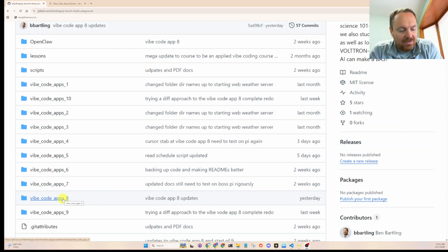Usually the mechanical engineer spec will say we need to create alarms, we need to log data for about a month, or some kind of specification on that. We need to dial out and notify the maintenance team if a failure happens to a fan or a pump or a motor or some critical equipment. We need to text and email out that there's a problem in the building. So I feel really confident that we can build this, especially with the help of AI writing the code. It's really powerful. It's getting better and better.